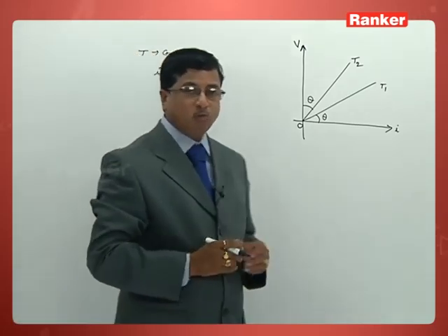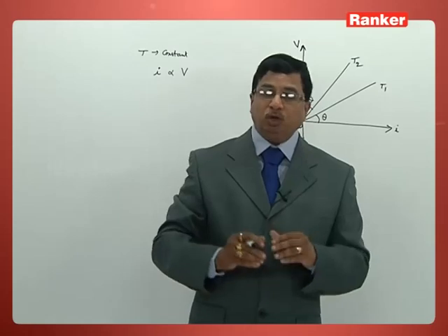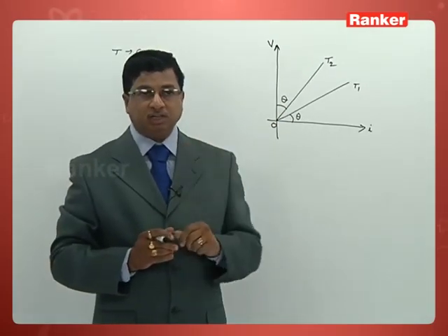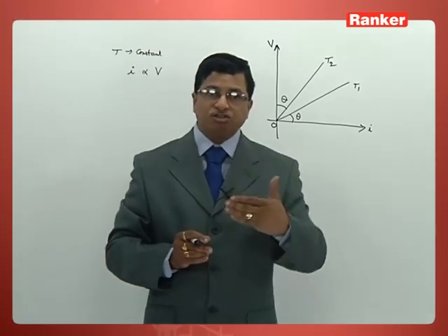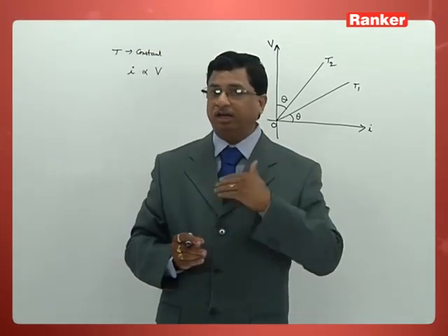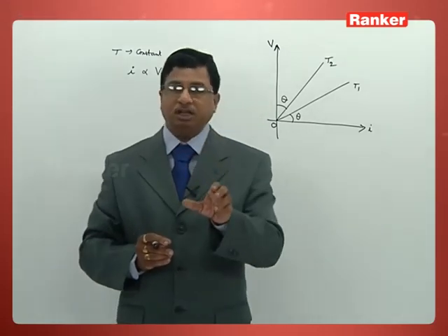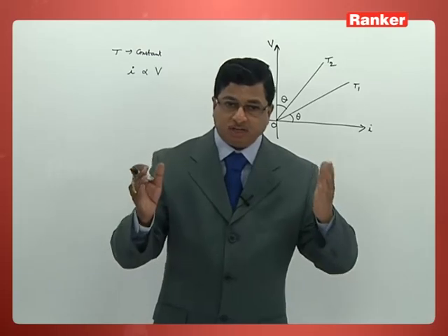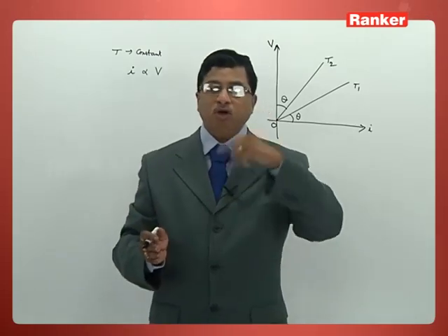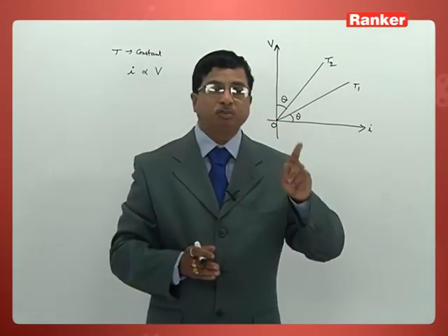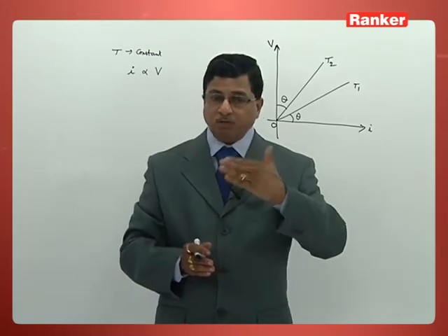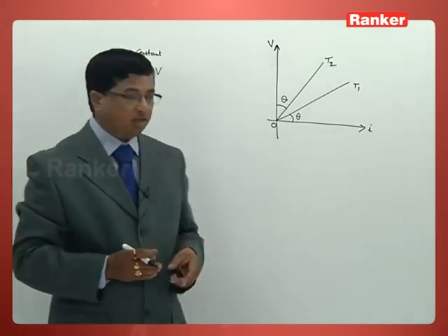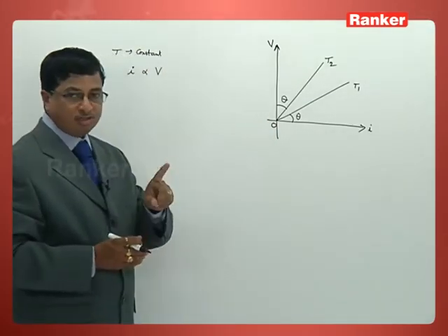Even though Ohm's law may not be a universal law, one can understand directly the exact relation between voltage and current whenever we consider a conductor. The more the potential difference across the conductor, the more the current passing through it. But one condition is to be mentioned carefully there, that is the temperature, which is supposed to be a constant.